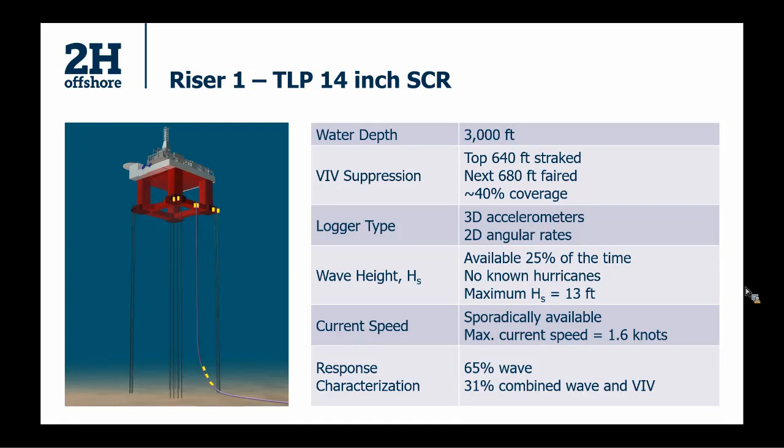And the response characterization, when we looked at the response of the riser, we saw that 65% of the time it was purely wave driven response. And 31% of the time there was wave and VIV as well. And we know that by looking at spectral plots. And I'll show you in a little bit.